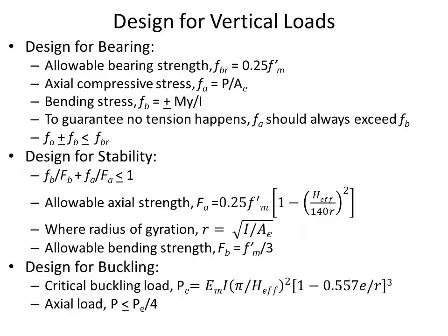And if you ask me what's the most common to see, the most common to see is the tension failure, actually, and the critical buckling failure, if you are talking about something with a high eccentricity. But if you don't have eccentricity, anything of that is possible, actually. The bearing could be even more critical in some cases.